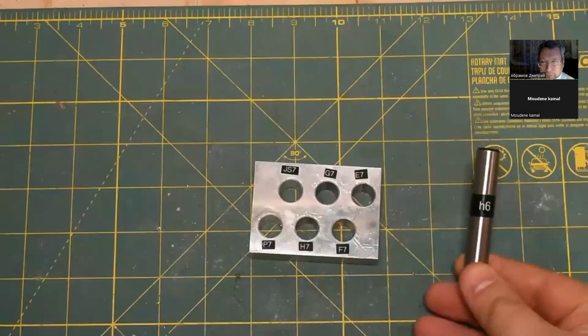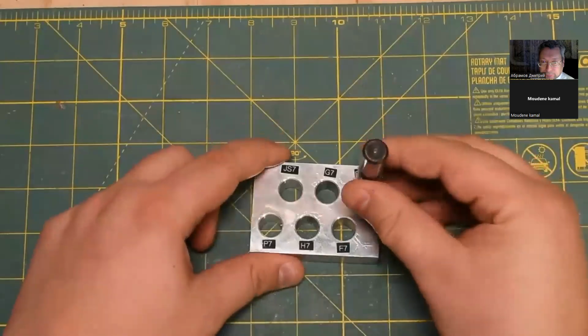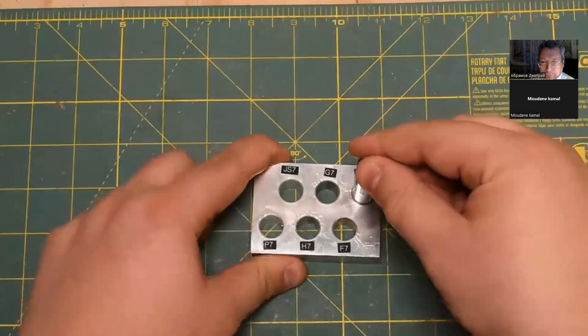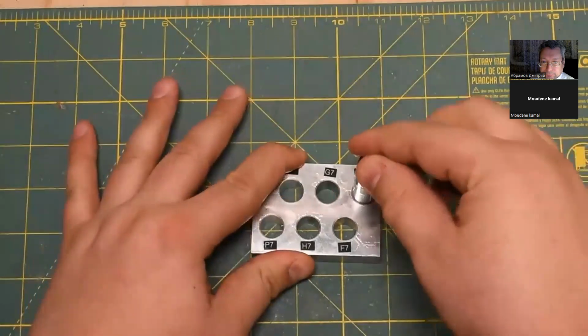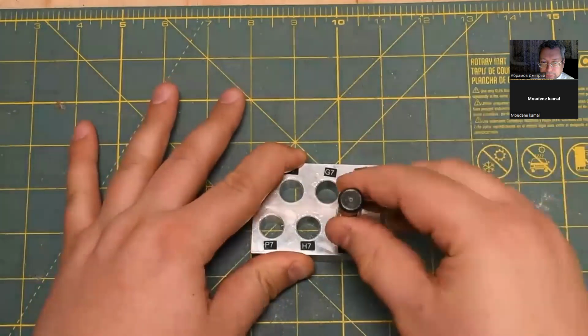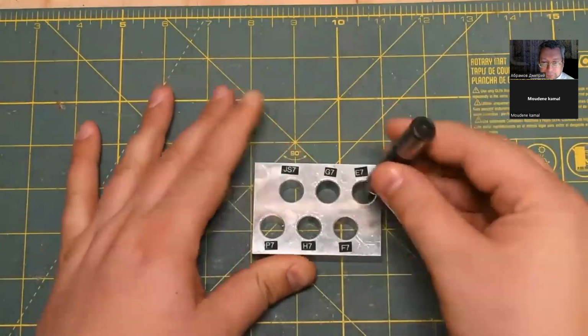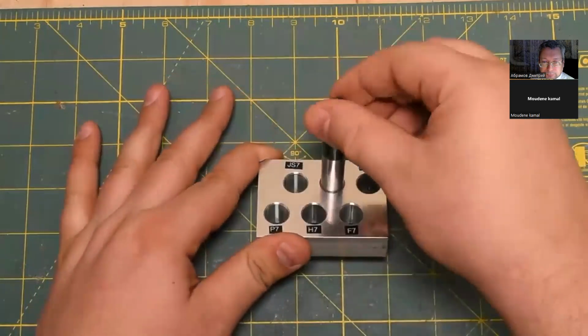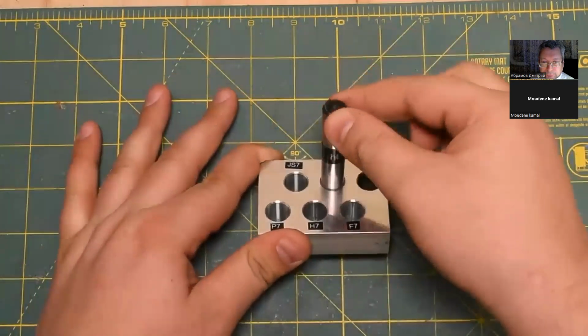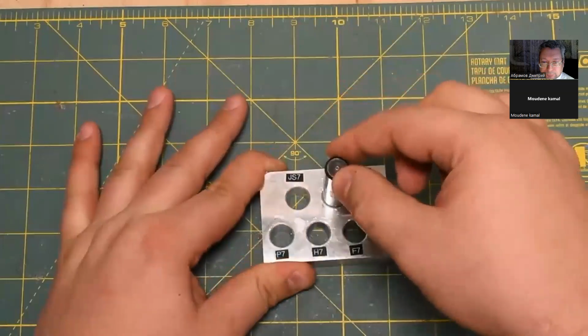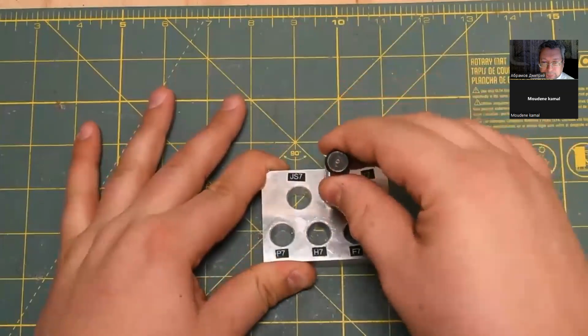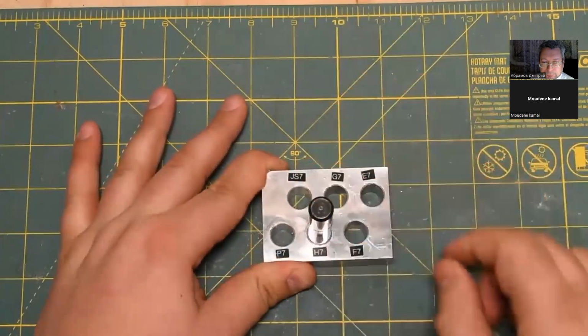I've cut some holes in this piece of aluminum to show some examples of different fits. This is an undersized H6 tolerance dowel pin. The E7H6 and F7H6 are reasonably loose clearance holes. You can rattle the 12.7mm H6 dowels around a little bit, and they basically drop right through. The H7H6 and G7H6 are much closer fits, and can perhaps be used to locate parts while remaining removable.